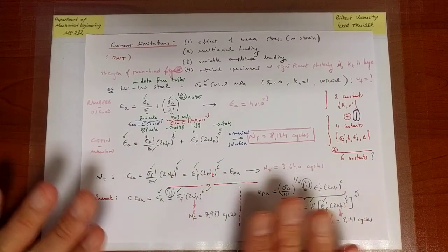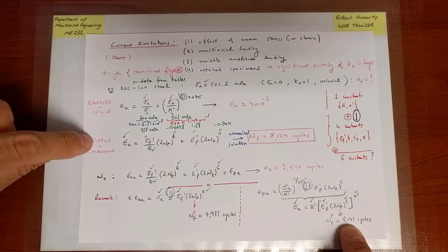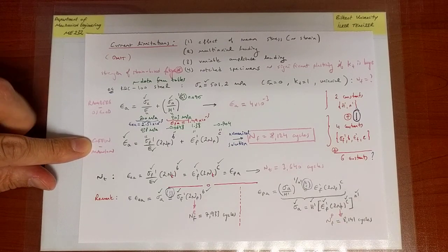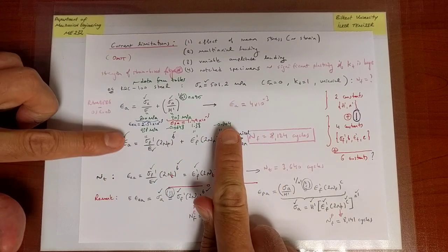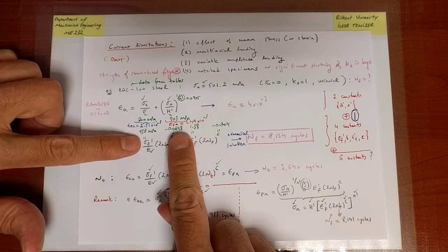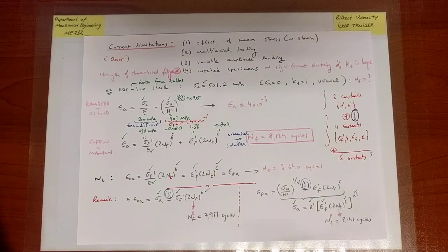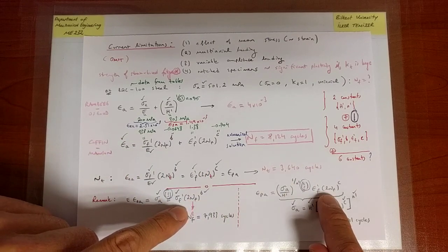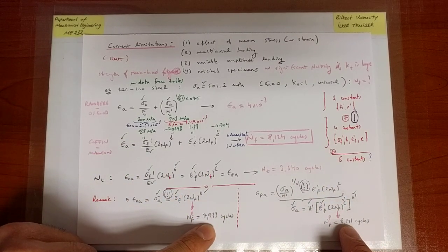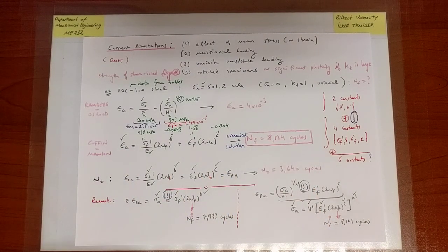So having said all of this and clarified the source of this discrepancy, let me tell you that the suggested practice is to go for the relation between total strain and number of cycles to failure. In other words, when you look at the Coffin-Manson relation, yes, the interpretation is elastic plus plastic, but we really are ultimately interested, from a modeling point of view, in the total strain versus life relation. And so we do not do this decomposition, because if we do, we can end up with slightly different results. The data is fit in order to predict this well. And therefore, this is our prediction. This is the best according to our judgment with this model.